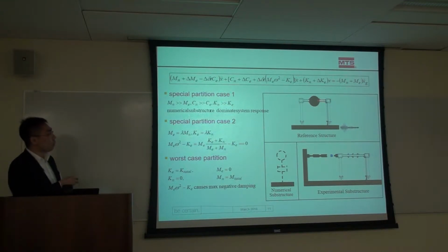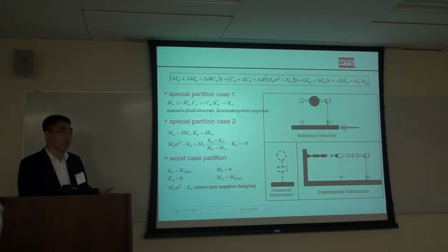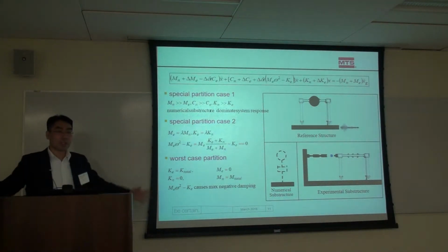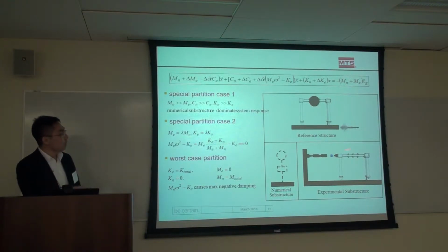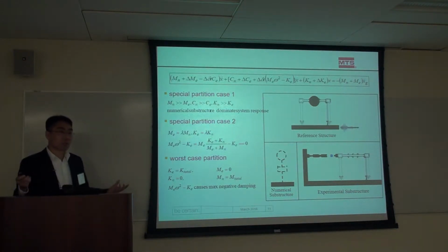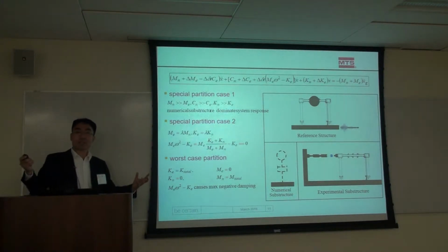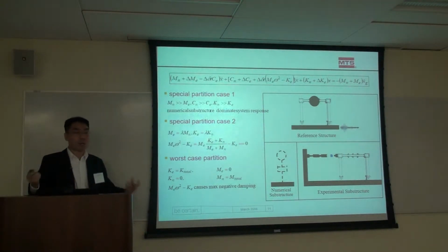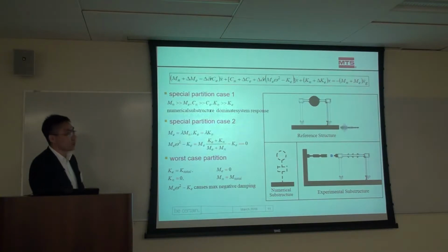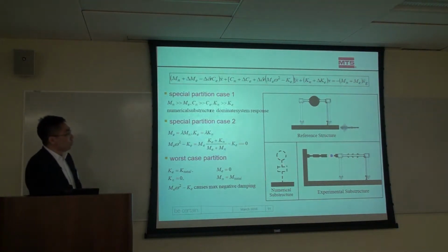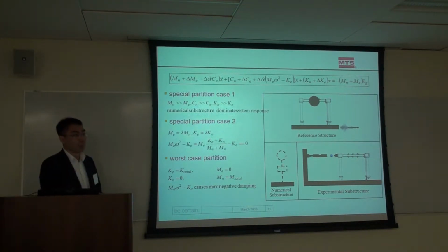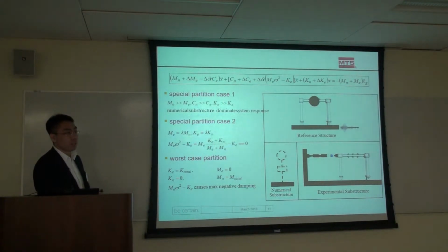Unfortunately, this is one of the most widely used test configurations in the quasi-static world, right? A lot of times we build the structural system that's our interest. We want to do a testing on it, then we don't need to construct a huge seismic mass on top of that structure. That's the merit of hybrid simulation. We can just simply assume the mass because it's easy to assume a mass. But when you do real-time hybrid simulation on this type of configuration, you need to be careful about it. It's very sensitive to the control error.